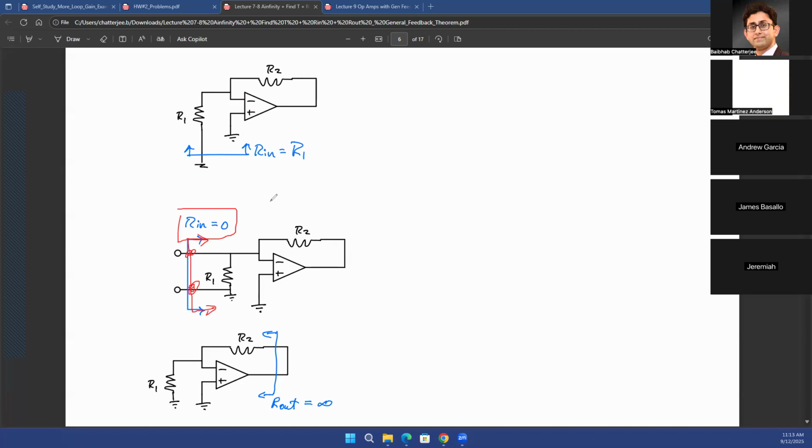Why is that? Again, say this is an op-amp connected in the negative feedback configuration because your output is going back to the negative or the inverting terminal, which means virtual ground property does hold. What is the non-inverting terminal of the op-amp connected to? It's connected to an AC ground. Since virtual ground property is applicable, the negative or the inverting terminal is also connected to AC ground effectively, right?